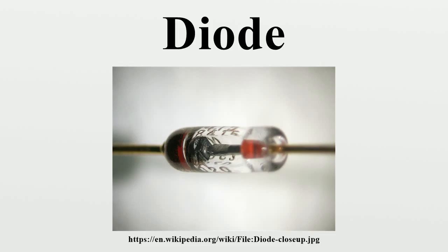In a mercury arc valve, an arc forms between a refractory conductive anode and a pool of liquid mercury acting as cathode. Such units were made with ratings up to hundreds of kilowatts, and were important in the development of HVDC power transmission. Some types of smaller thermionic rectifiers sometimes had mercury vapor filled to reduce their forward voltage drop and to increase current rating over thermionic hard vacuum devices.